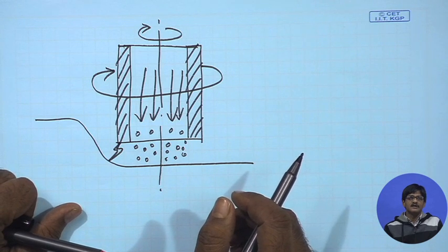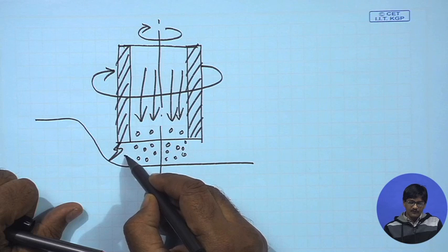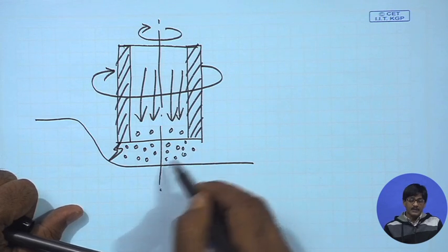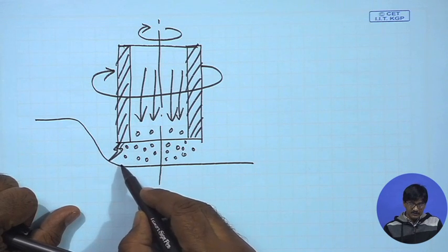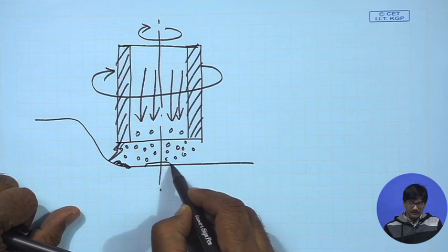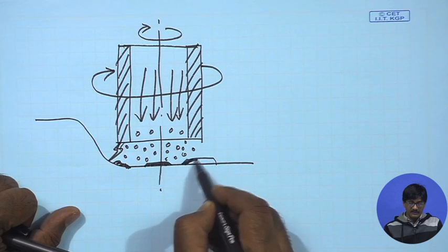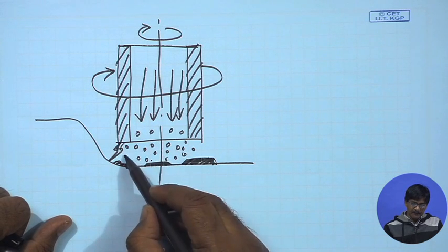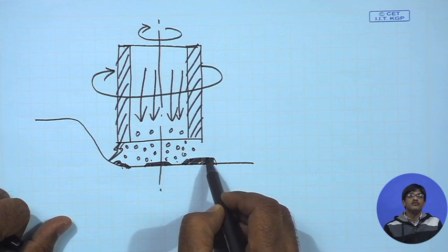That means surface integrity will not be of very high quality. So if these abrasives are coming, they will find that at this edge EDM has taken place and maybe a recast layer has formed on the surface which we call the finished surface. Abrasives will impact this recast layer and be able to remove it.